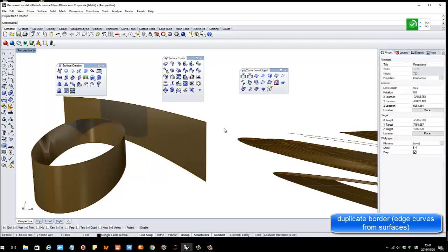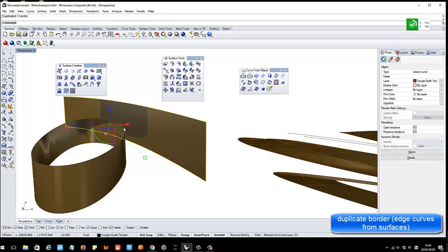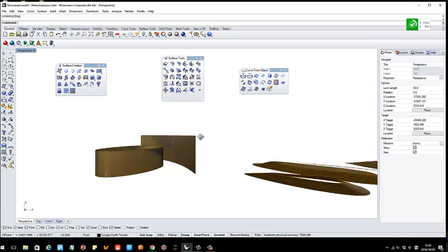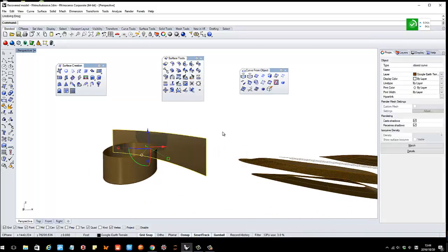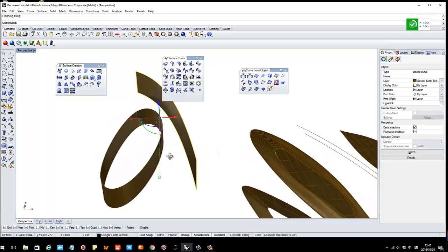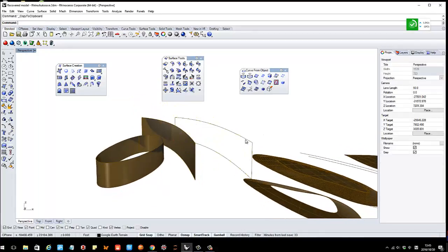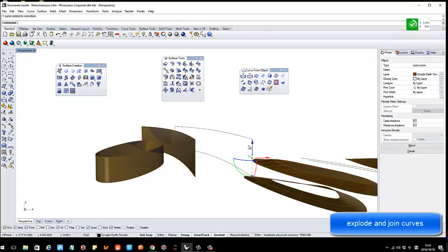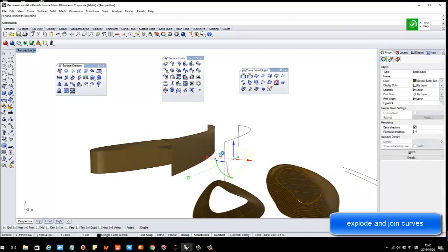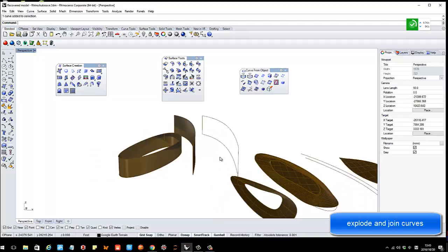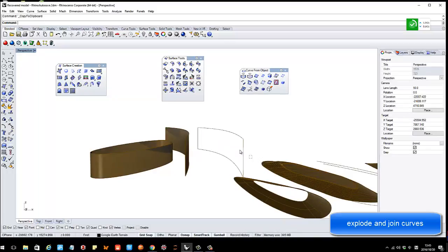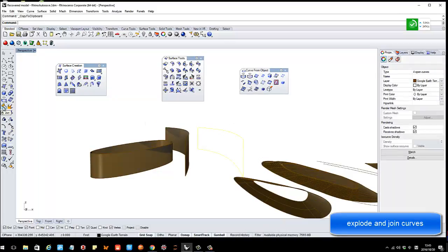Once you click that, you select the objects and click that, then you can see they already created curves for you, which is all the edges of the lines. And what you can do is really easy. See here, it has 4 segments, right? When you click 4 segments, then you just click this explode. Then it turns into single parts. Explode will explode all the curves, because this is made by 4 different curves, right? And if you want all these 4 curves as a single one, you just click this one, join, and then they turn into a single one.